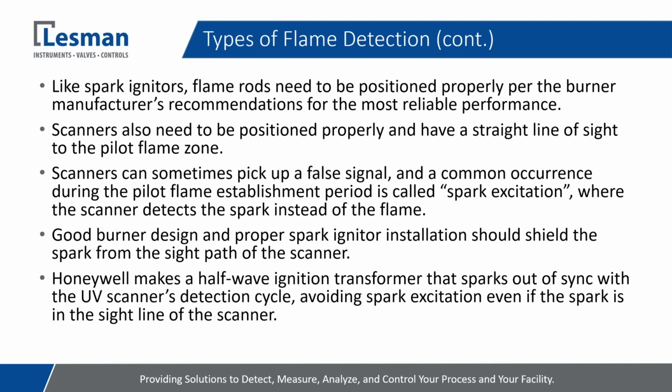A good burner design with the properly installed spark igniter, it wouldn't be detected. There's some kind of a shield or some method where it's sparking at an area of the pilot zone where it's not being detected by the UV scanner.